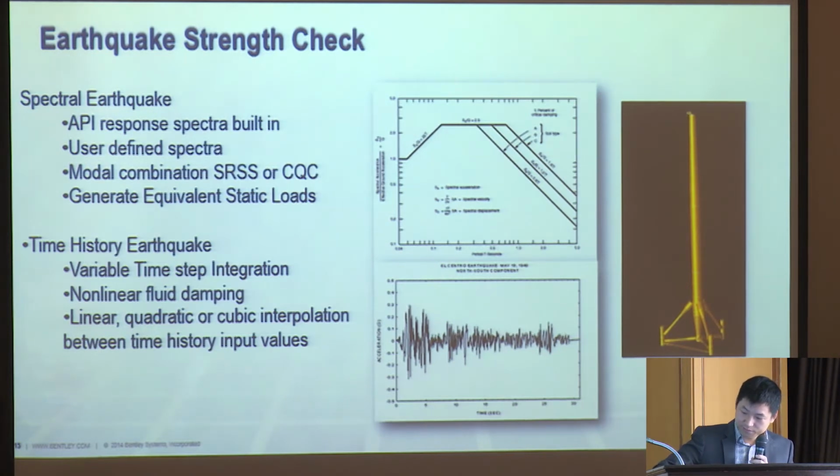For example, if you want to do a ductile level earthquake (DLE), you need to generate the equivalent static earthquake load for the collapse analysis.